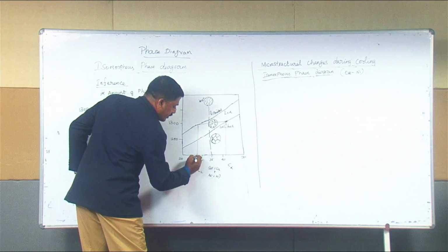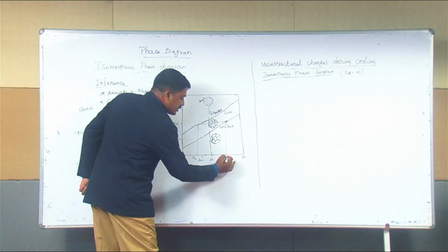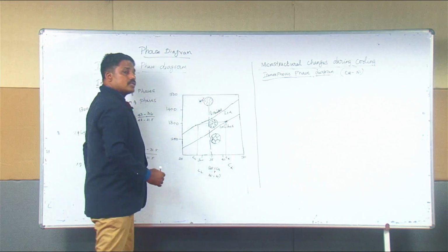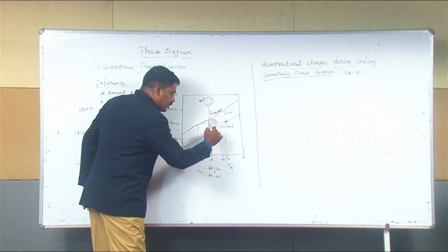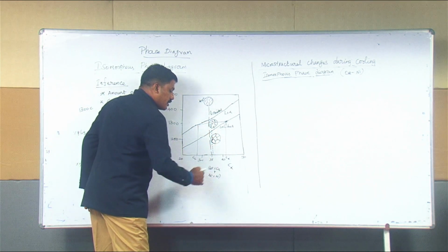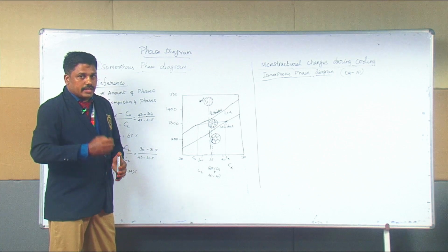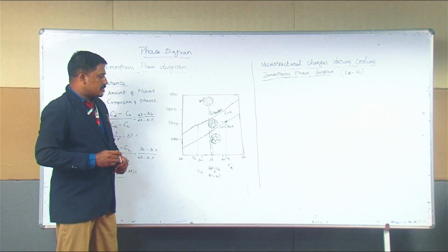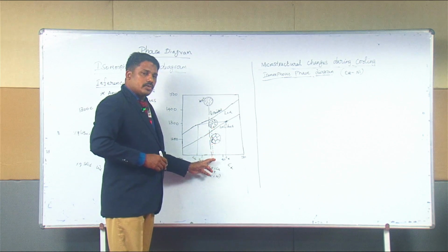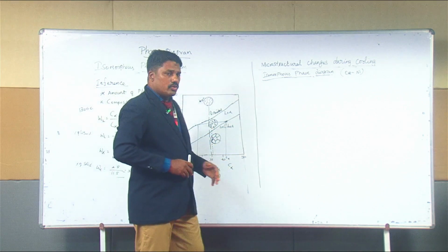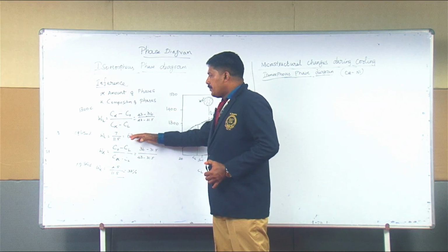The line drawn from the liquidus boundary gives the liquid composition, and from the solidus boundary the solid composition. Using the lever rule, we draw a middle line representing the equilibrium condition, and that value is C0, the overall composition. Using these values, we can find the amount of phases present.